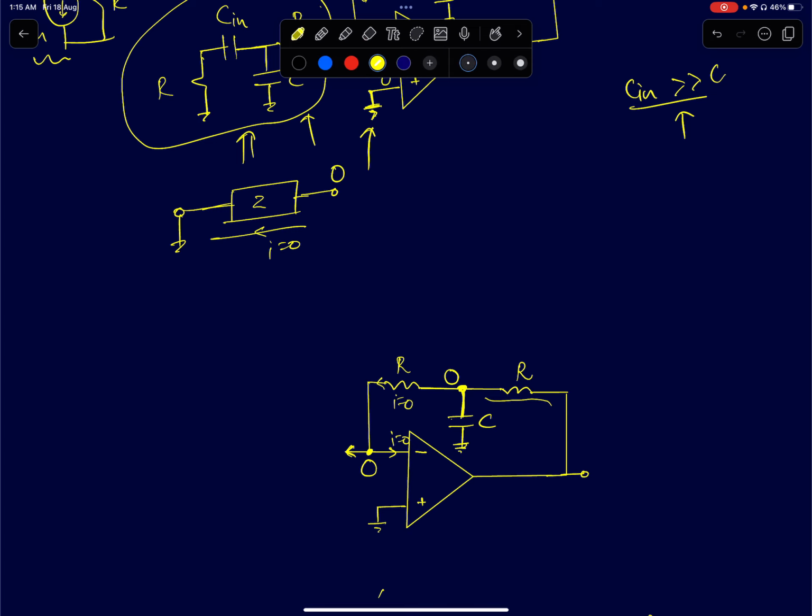Because I will be interfering with the negative feedback. I want to capture the feedback in action. So I can't drive this node with a voltage source. If I drive it with a voltage source, I'm killing the op-amp feedback action, right? If I'm driving this node with some Vtest and trying to measure the current, then what am I doing? I'm forcing this node to be at AC ground. So the op-amp has no reaction to it. By the time you apply any test Vx here, this node voltage is always fixed at Vt. So I can't do that.